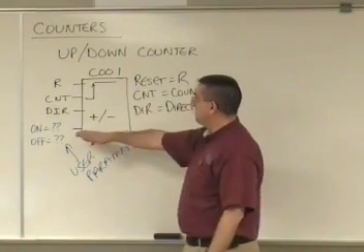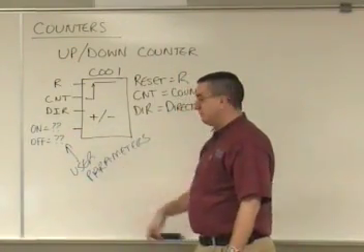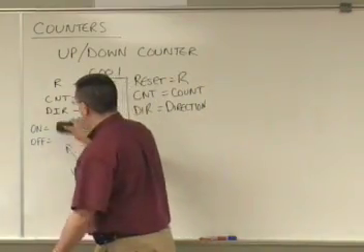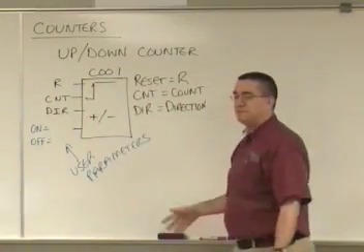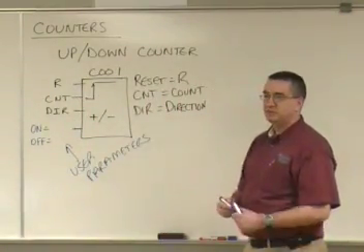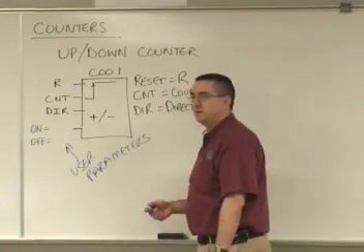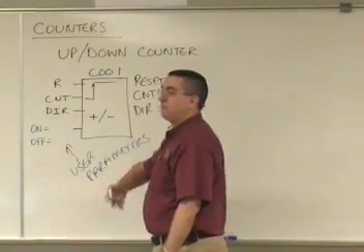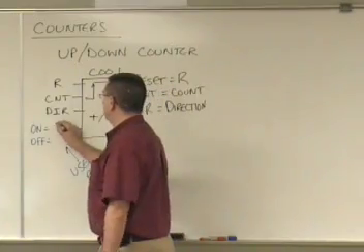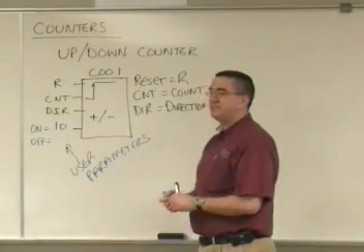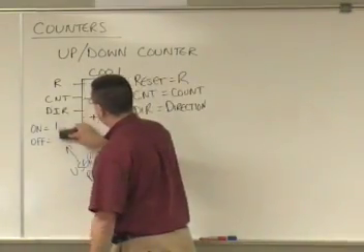The blue pin is going to be my on and off threshold. My on and off threshold is just a variable. Okay, so what might I put in there as an on threshold? How many times the system goes off. Yeah, how many times before that counter bit energizes? So maybe on the 10th time, or let's change that. Let's make it the 12th.